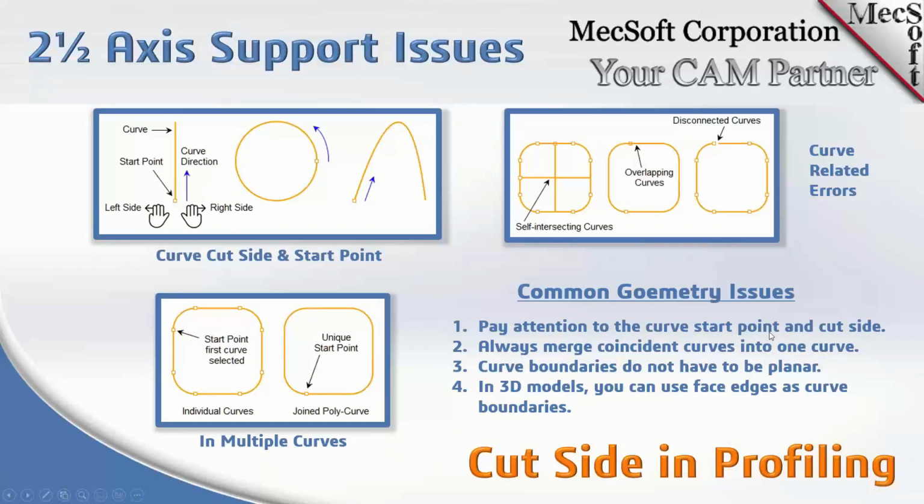Always merge coincident curves into one curve. We mentioned that a number of times. Very important. Your curve boundaries, understand they don't have to be planar. If you have planar curves, that's great, just select them. But they don't have to be planar.